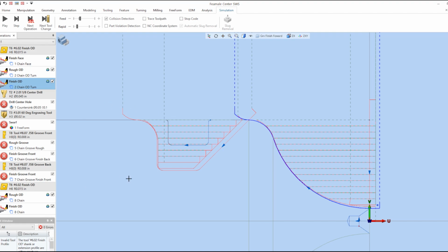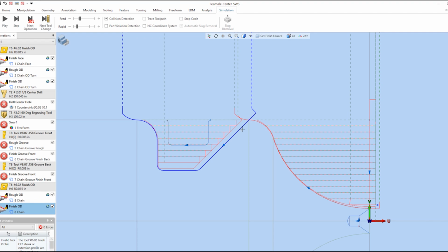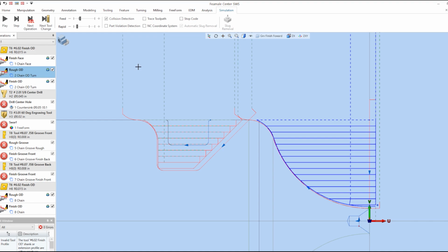And then this one, this undercut area, you can see how it looks. See how the toolpath for the roughing cycle looks? And this is the finish cut, which is the actual shape of the part using tip compensation. There's nothing special about this. It's just a fake part, just for the purpose of demonstrating this. So note the toolpath, the way it looks right here, for instance.